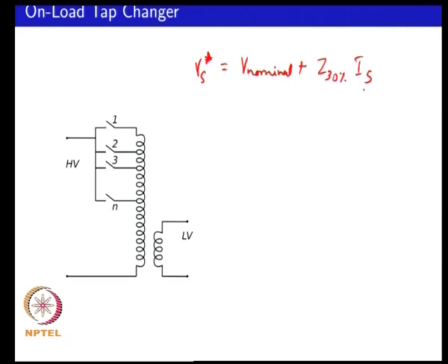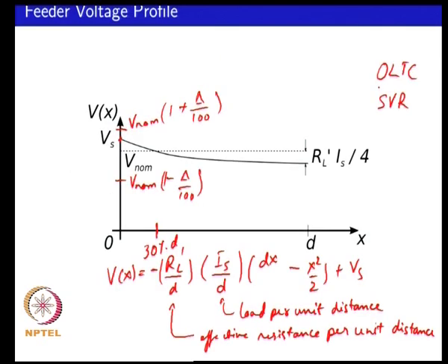So, you are making use of the line currents that you know that is coming through the feeder to actually predict what is the voltage that would be there at 30% distance down along the feeder. So, essentially you are adding a boost term to the voltage, so that the boost term would correspond to essentially this particular value above the nominal which you are trying to boost.